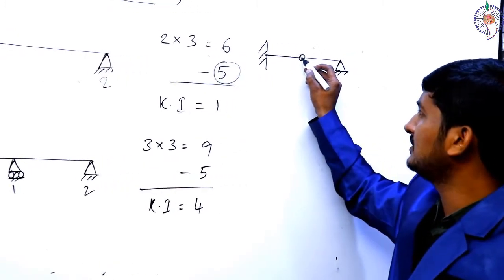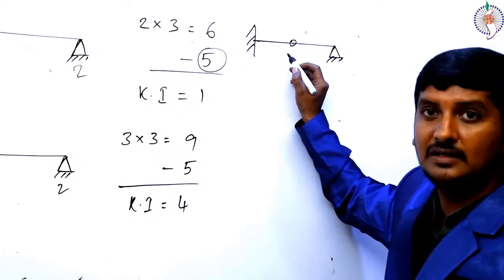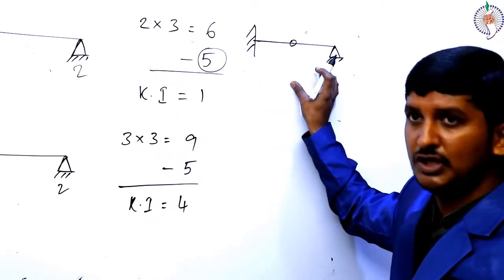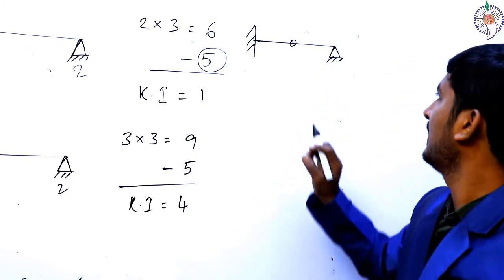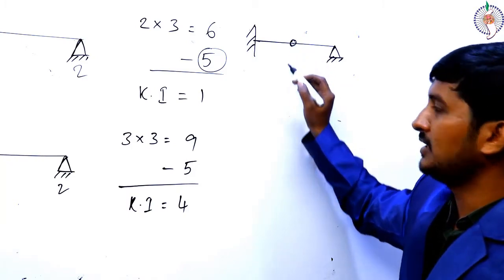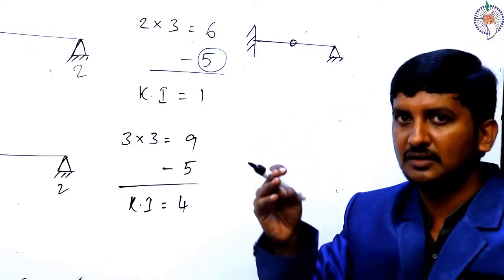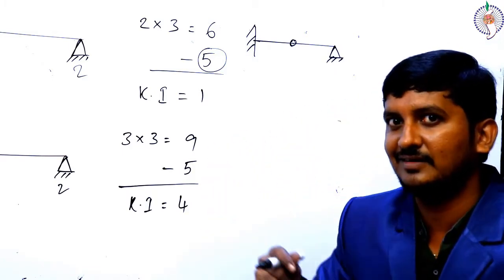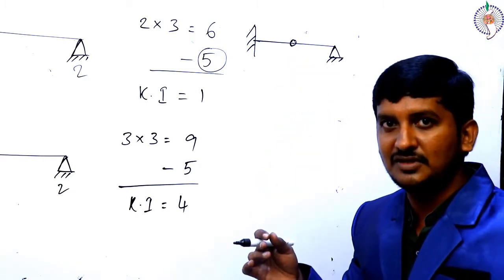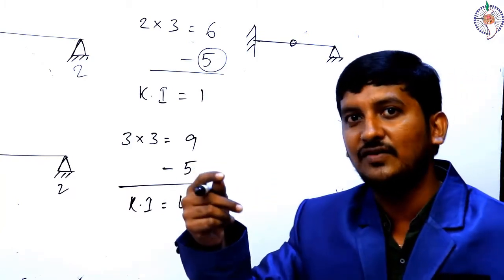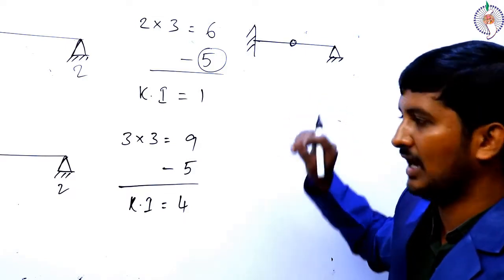What do we call this? As I already mentioned, this is an internal hinge. In calculating static indeterminacy, I have posed the same question. Right. Here we need to calculate kinematic indeterminacy. So, don't bother about this internal hinge. When it comes into this picture, just remember that some addition is going to happen. In static indeterminacy, what we have done is, if an internal hinge comes, we add an extra equilibrium condition. Right, students? Here we are going to do a similar thing, but in another way.